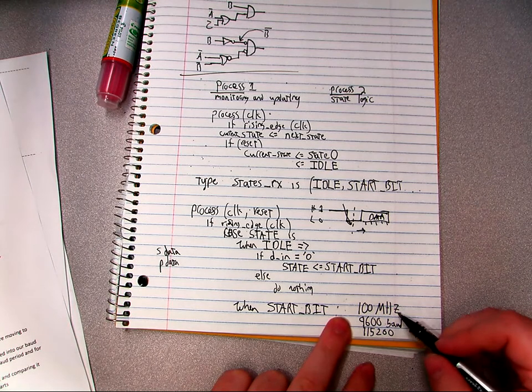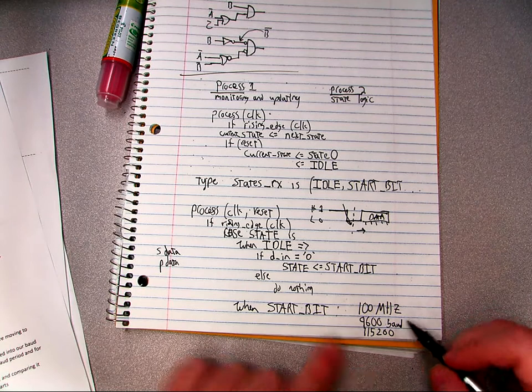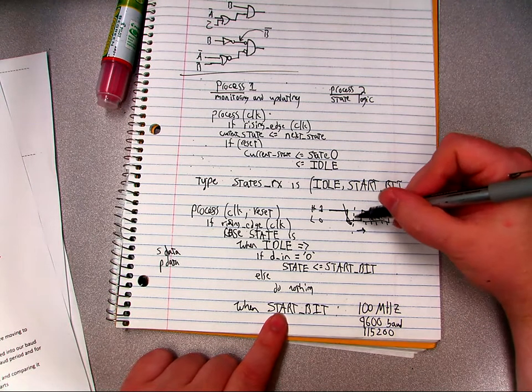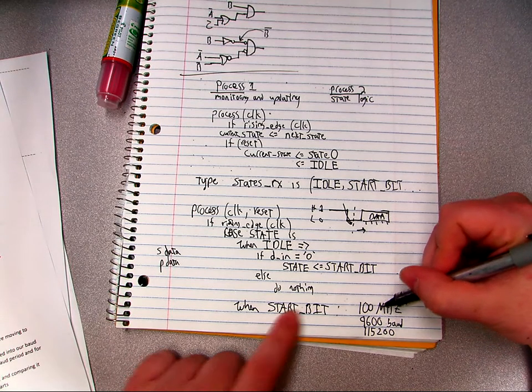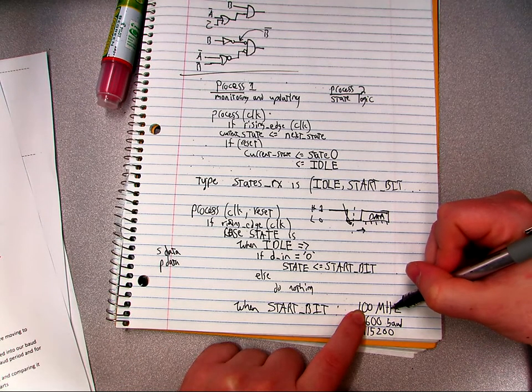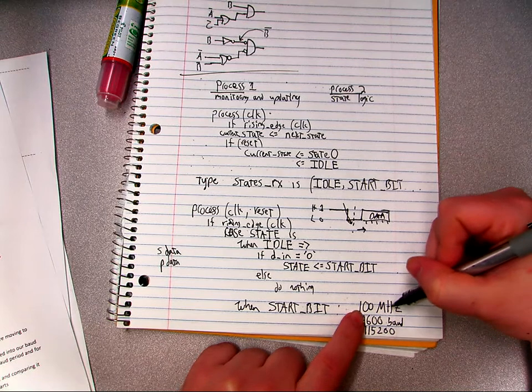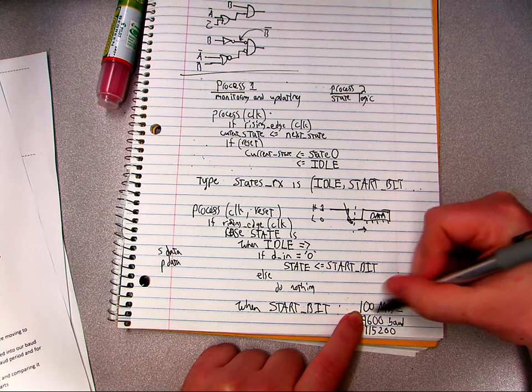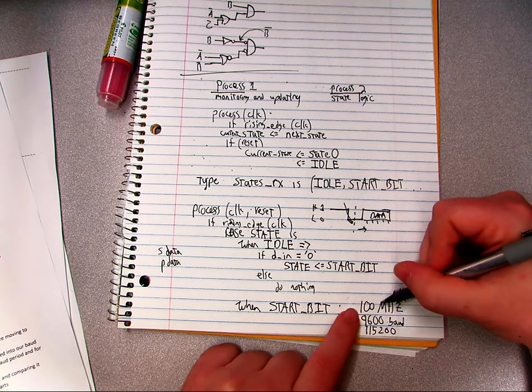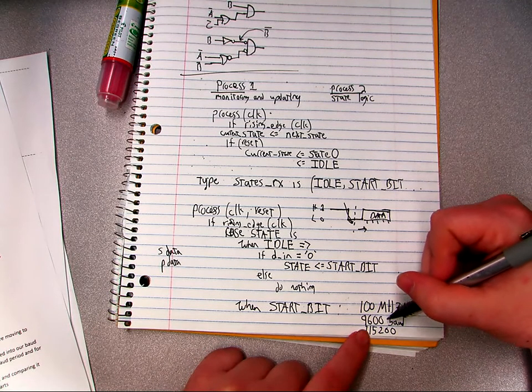Okay, so what that means is this wait period is at your baud rate. But you need to convert from 100 megahertz. So what that means is we need a way of counting 100 megahertz for each baud, doing that conversion of 100 megahertz to baud and how that correlates to a time period wait.